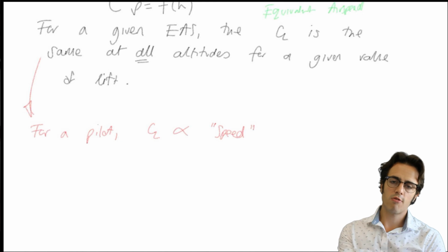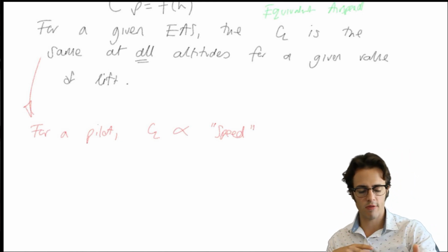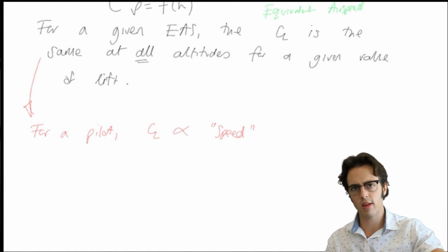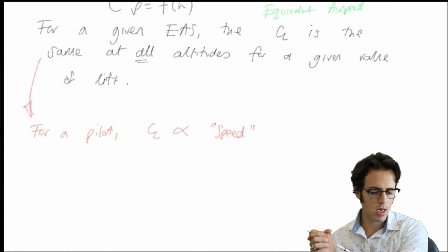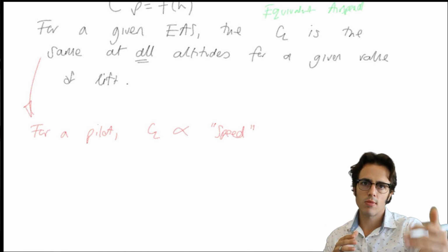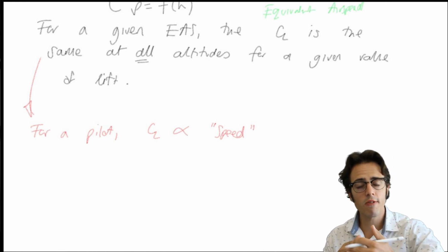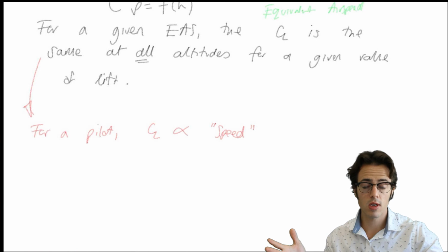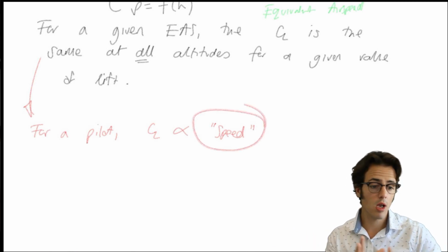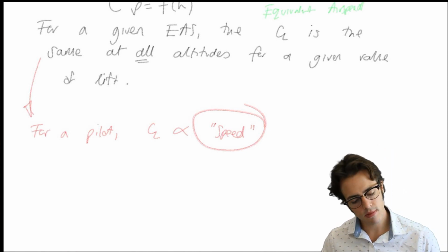So for a given value of dimensional lift, we know that at a certain dimensional value of lift, that's the maximum the wings can take. And we'll cover this in more detail during load factor, etc. If we are using true airspeed, that fixed maximum value of lift corresponds to different CLs depending on altitude, which means that it corresponds to different speeds dependent on altitude, which means that the maximum speed of the aircraft changes with altitude.